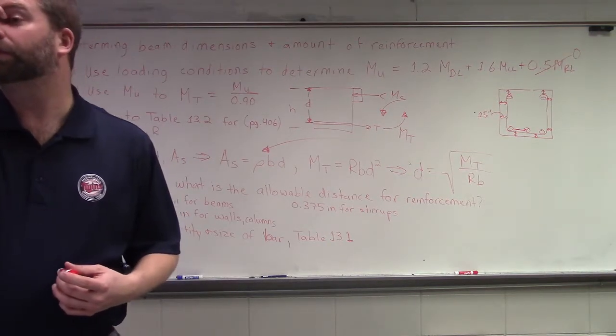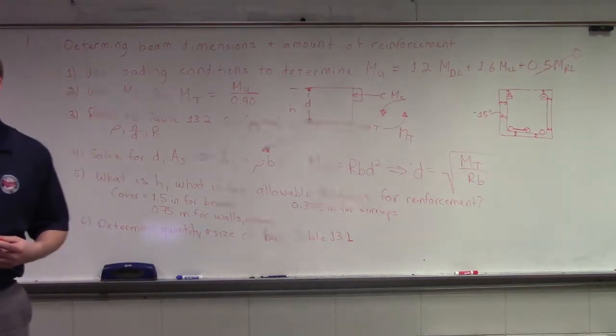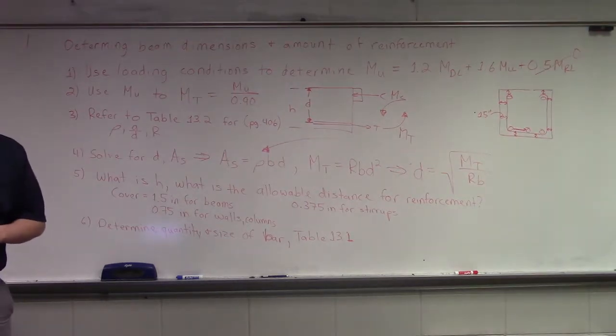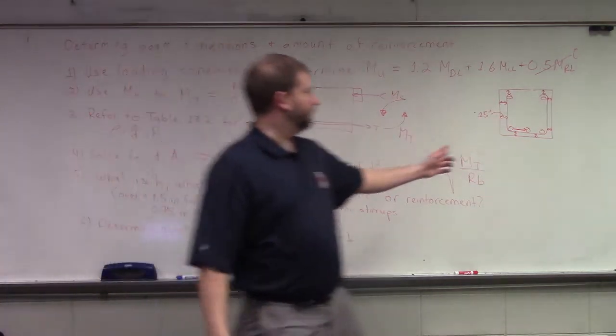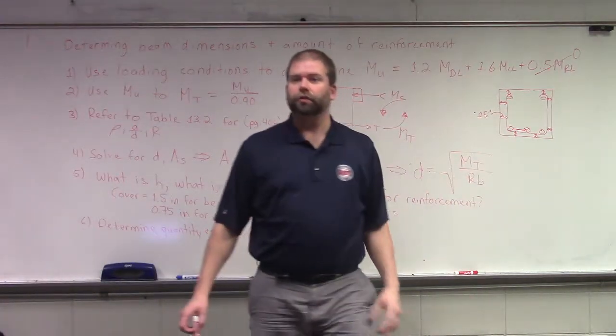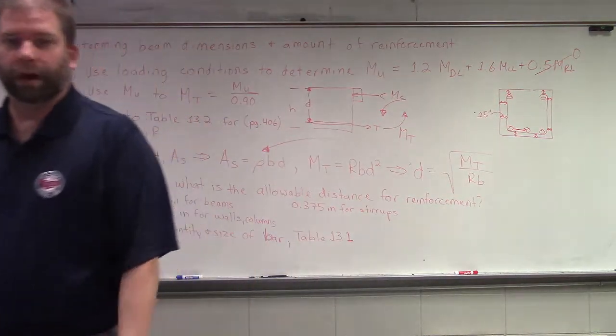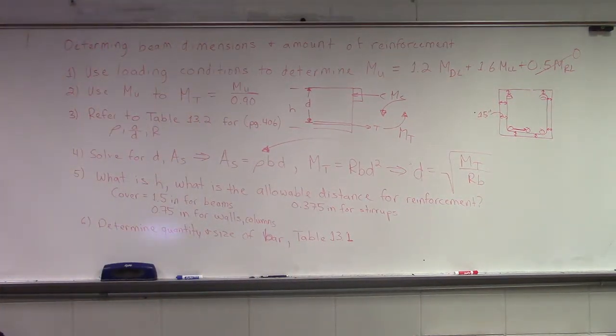Do you have a follow-up question, Steve? So your spacing should be a minimum of 1 inch? Well, we would like to, but it may not be the case that we're able to. So if you need to reduce it, don't reduce it smaller than the bar width. But whenever you can, I'd like to see that at 1 inch. Whenever possible, okay?